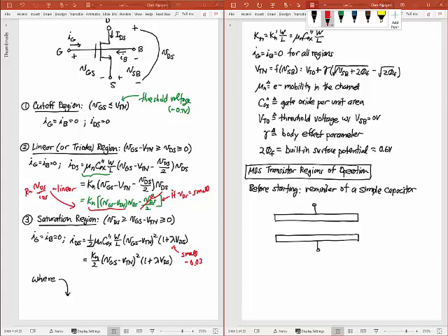But if ever you get lost in this, this is all you have to remember. If I have a capacitor like this, and if I put a voltage across this capacitor, like this, and say I call that voltage VG, what's going to happen in that capacitor if I put that voltage across it? I'll build up an electric field, yeah, that's true, and we'll be using that. But the other more important thing is I build up charge on those plates, right? All I'm doing is putting charge on the plates.